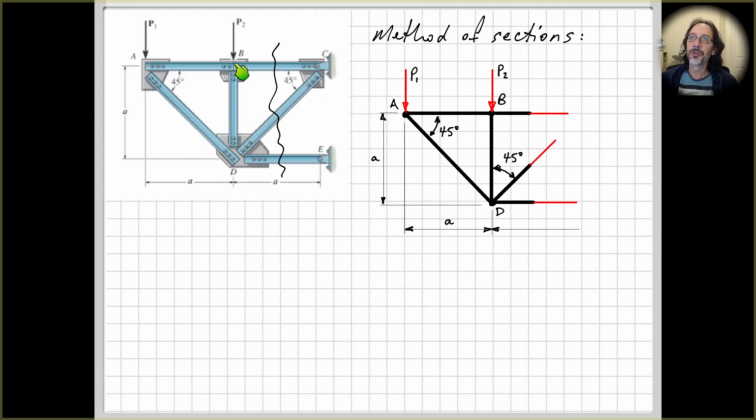In reality, because we've got these bolted and gusseted connections, there will be some bending, but we're ignoring that for this problem. Right, so we have forces directed along the lines of each of the truss members. Okay, so you can just assume the sense of these forces, or you can try and work them out, right? Or just make them all in tension, and then if you get a negative value, that'll tell you it's in compression, right? But I usually like to try and work them out.